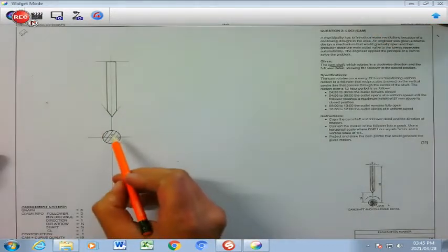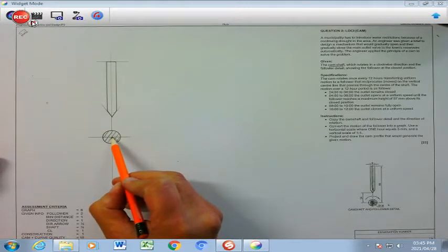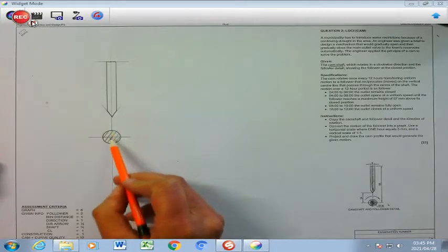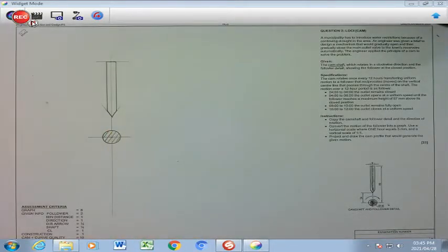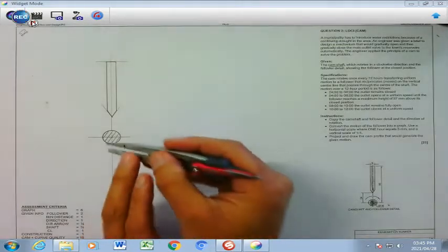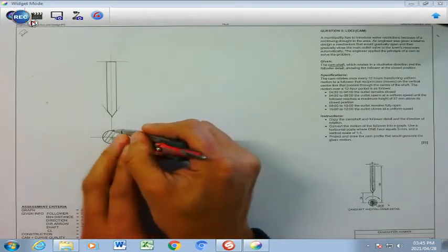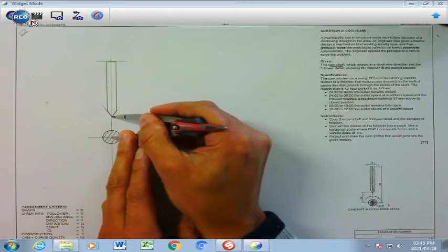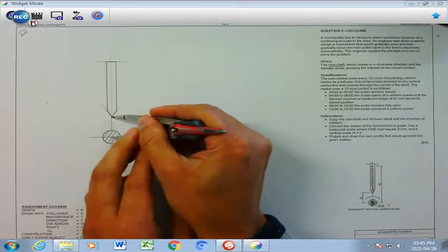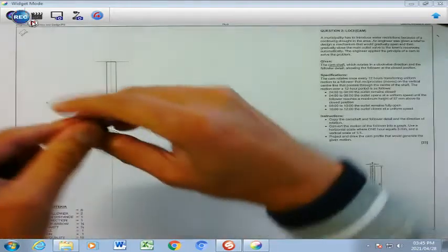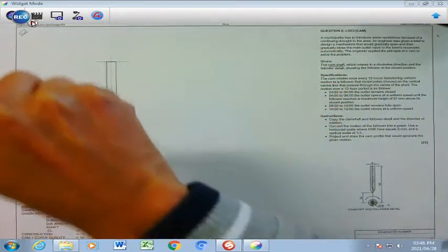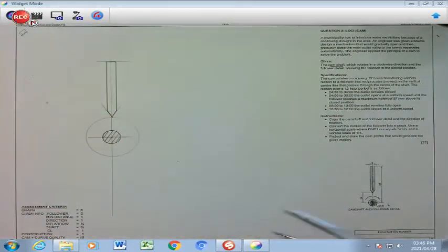Then the area between my center of my cam shaft and the tip of my cam follower, that is going to be my minimum radius. I am, however, going to take my compass, anchor it in the center there, open it up at the bottom of that cam wedge follower, and then I'm going to draw a circle like that there, and that basically would be my minimum radius.